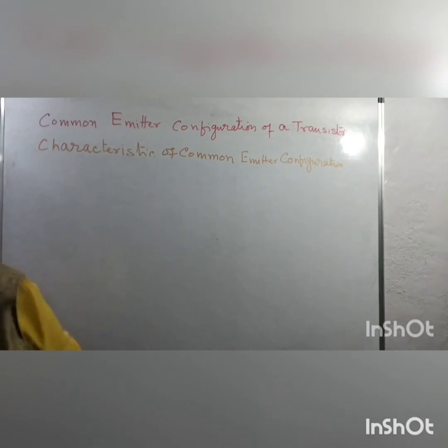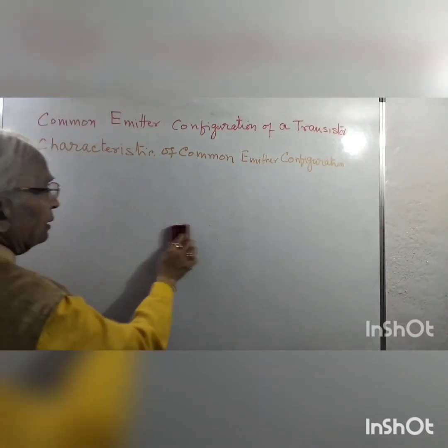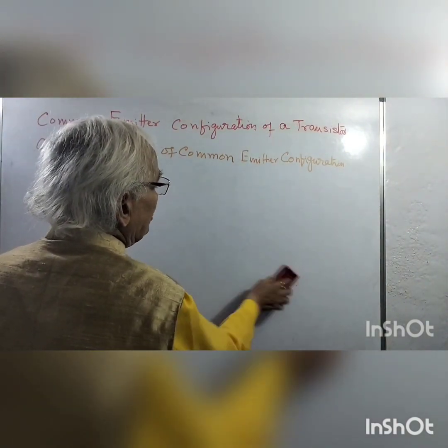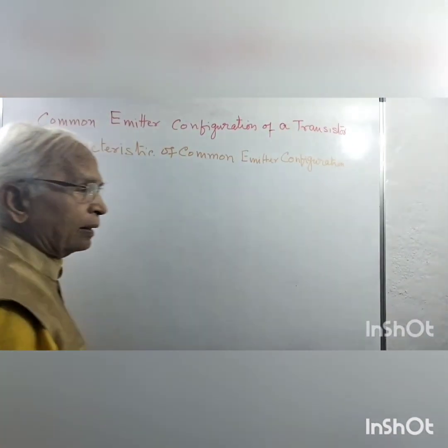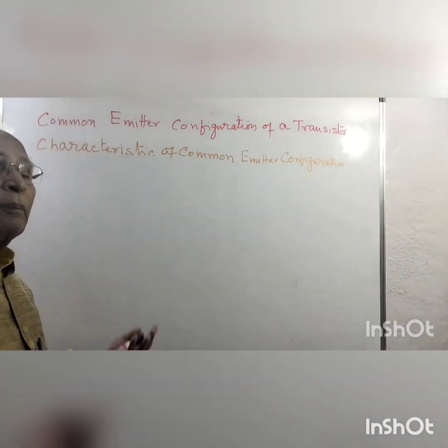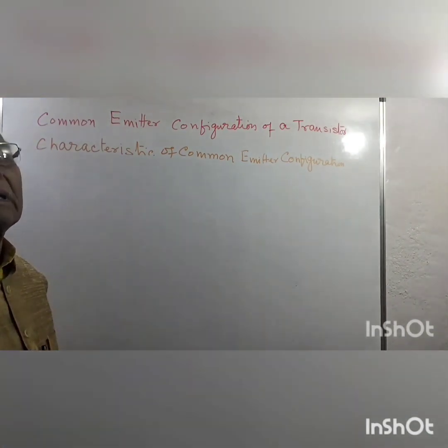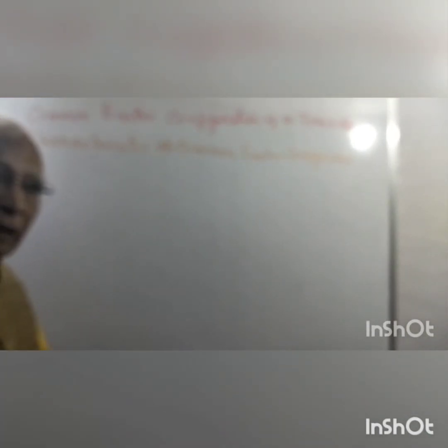This happens many times with students in the laboratory, that current doesn't flow. They come to the teacher: sir, current is not flowing, the transistor is not working, it is bad. But actually, the potentials are not properly applied. So check the potential terminals of the battery and then see.